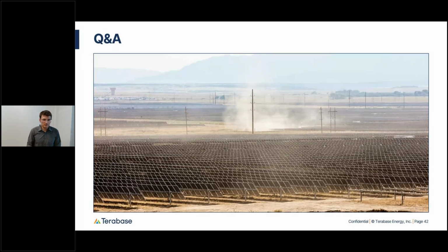If, however, you have a dusty road, or a mine, and you're building right next to that mine, then I would recommend going for a preliminary or pre-construction soiling measurement campaign. And to answer the second question, yes, it is possible to fine-tune model parameters based on these measurements.